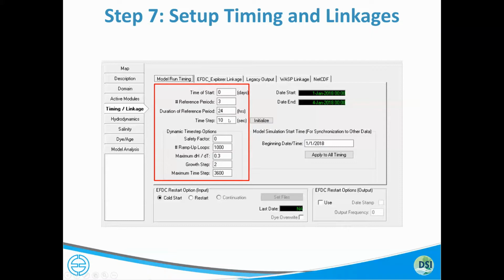You can, of course, maybe during model testing, raise or lower it according to more of the details of the actual model configuration when you're running some tests, but this gets you pretty close to what it needs to be. When you're doing a 2 time level solution, which we won't get into the difference between 2 and 3 time level solutions right now, you can also use dynamic time stepping, but when this is set to 0, dynamic time stepping is not used. So in this case, we're not using it.